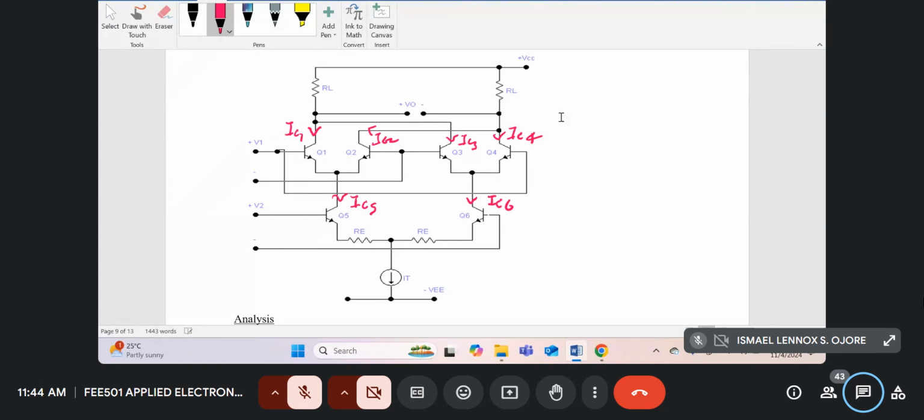Okay, so let's start. If you look at this diagram over here, the signal current IC1 of the collector comes to the emitter. The signal current IC2 comes to the emitter. So IC1 and IC2 add up to form the collector current of this bottom transistor.